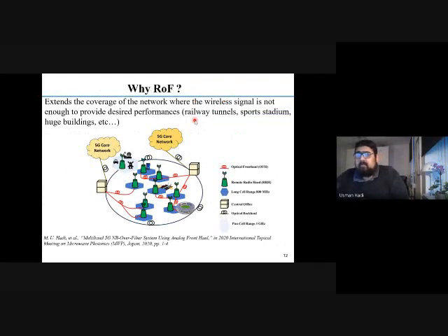What you have seen previously in the animation, this is just a block schematic diagram to explain that generally you have a 5G core network. You have the centralized office for the signal processing. This is the backhaul, and then this is the optical fronthaul that we are involved in. So this optical fronthaul that connects your centralized office to different remote radio heads, the towers, is actually the radio over fiber.